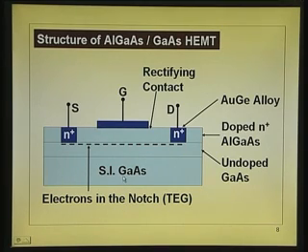semi insulating gallium arsenide, which is actually the substrate which holds that active layer. On top of semi insulating gallium arsenide you grow undoped gallium arsenide, which will be 10 to the power 13 of that order, or even better if you have a better way of growing. So, a thin layer that could be just 0.2, 0.3 micron thick, because it is after all to support this notch. You provide this gallium arsenide, and on top of that you put this N plus layer, that is aluminum gallium arsenide. Okay.